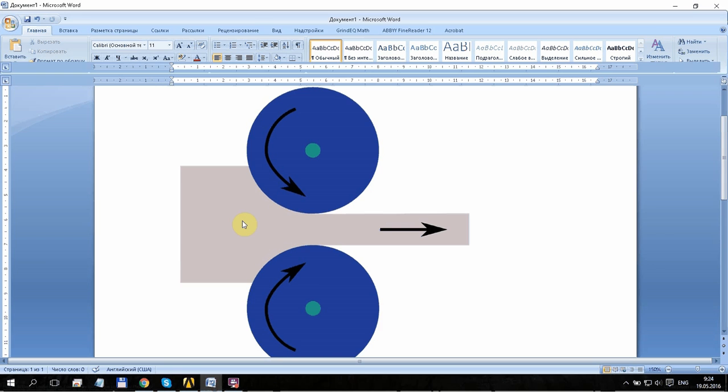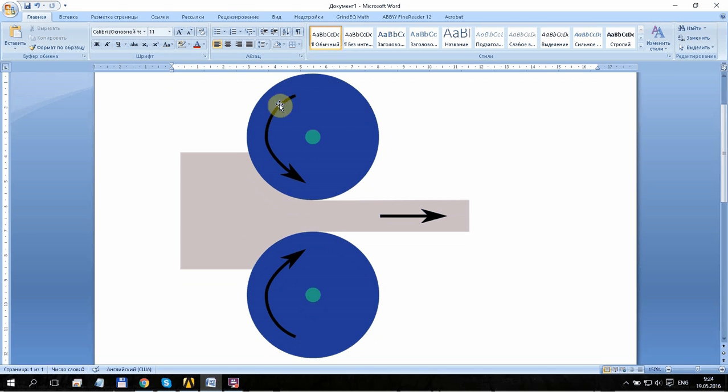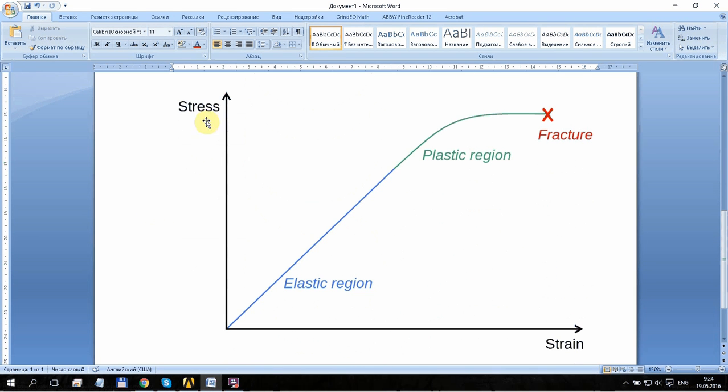So first of all, the problem is about rolling and plastic deformation of metals. These are the common instructions for how we simulate it, and we will try to make almost the same geometry. However, you can see here there is a symmetrical axis, so we will use this condition to make our simulation easier. The first thing you should know about this problem is that we need to use nonlinear properties of material,